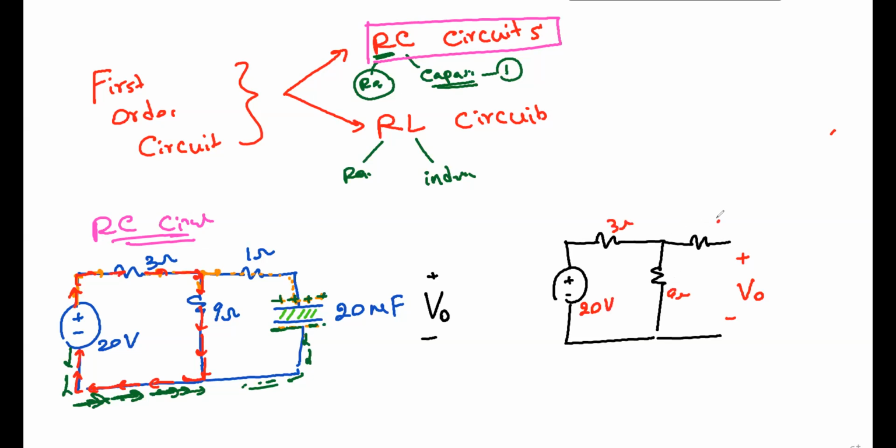So how do you find the V naught? This resistor is not functioning because there is no current going across that. Am I right? V naught is the voltage across this 9 volts. Do you agree? This is your V naught, isn't it? Right, because they're parallel anyway. They are parallel, yes. So this is not functioning. So these 2 points and these 2 points are the same points anyway, isn't it? Because you don't have a resistor over here. So that's the same 2 points, isn't it?